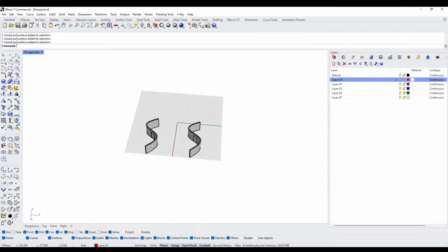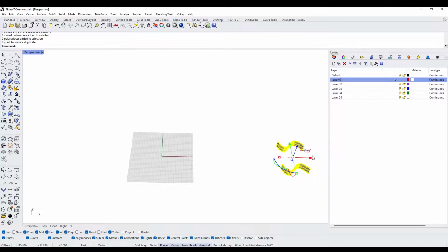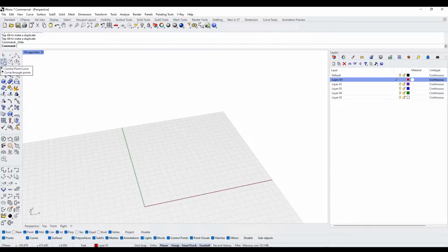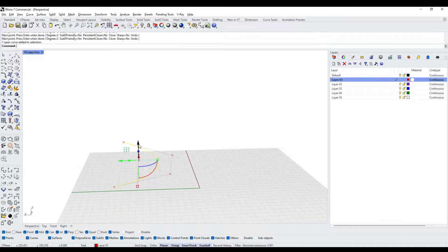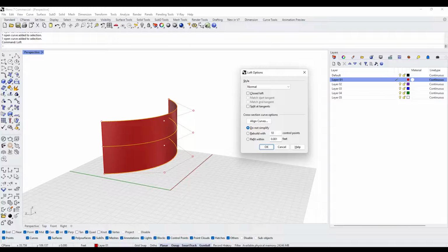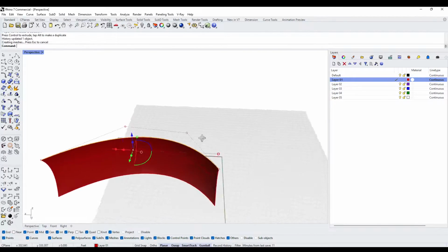So let's create another iteration that I want to show of a curved wall. But this time, we'll move it to the side, Control H to hide. And this time, I'll be using a NURBS curve just to change it up. I'll pick 4 points. I'll take this, Alt, copy up, and then Alt, copy up again. Then I'll take these three, loft it together, and then use record history. This way, when I move the curves, it will move it with it.